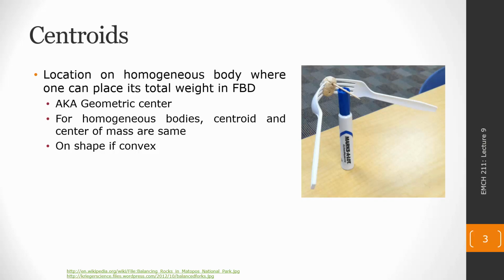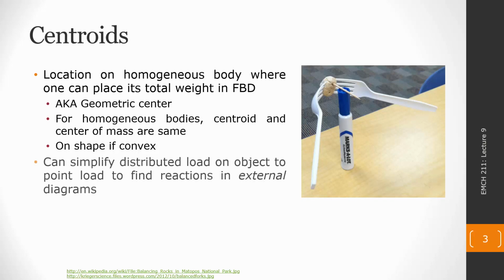Finding the centroid or the center of mass not only lets us simplify all of the mass in the body to a single point, but it's going to allow us later in this section to simplify distributed loads to an equivalent load acting at a single point. So if we have force on our object due to something like sand or snow where it's distributed across the body, we're going to be able to simplify that load to a point load and then work with it as we have been previously in this semester.